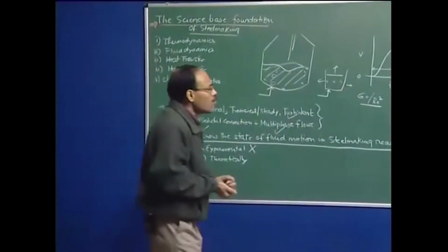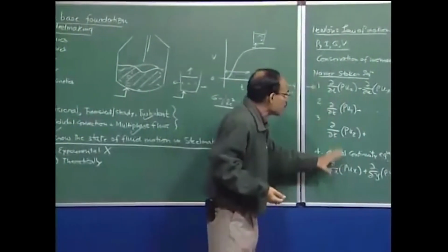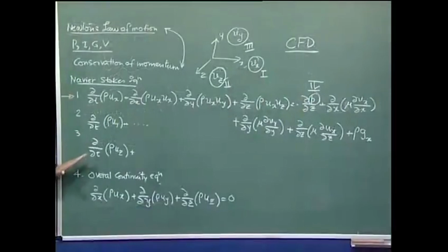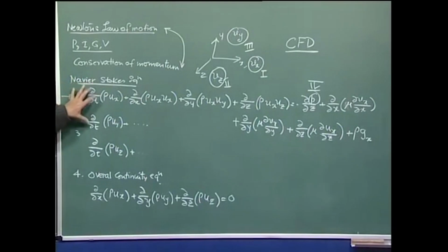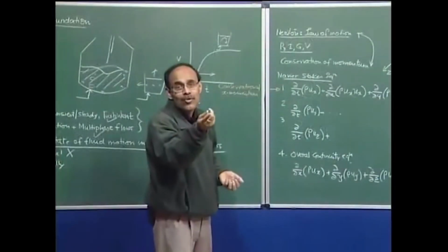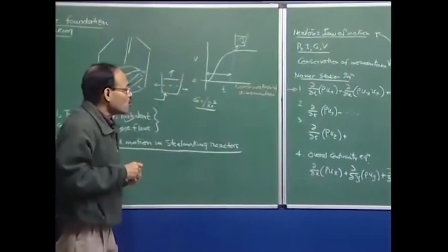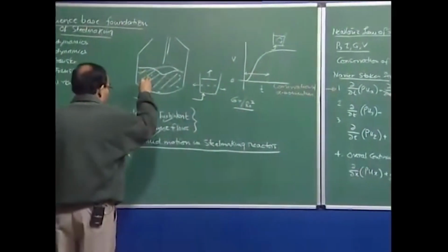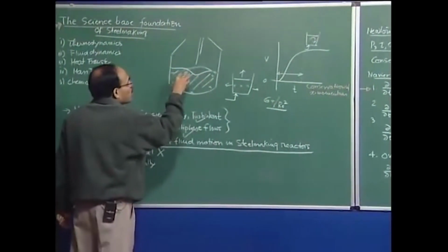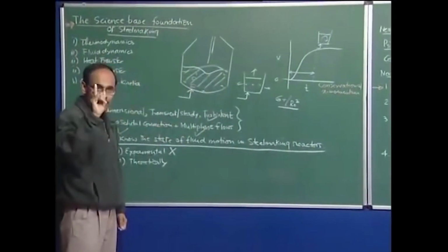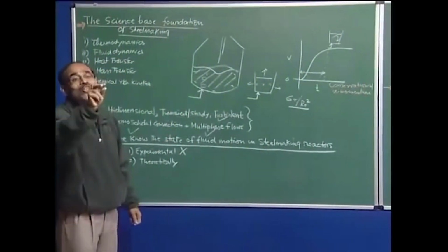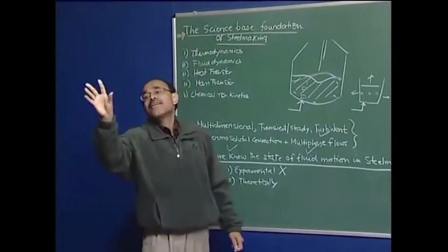Now, you can have just 4 equations, for example. On top of this, as I have mentioned, if you have thermal buoyancy, if you have solutal buoyancy, in that case the flow is going to be influenced by thermosolutal convection also. So, the flow is going to be related to heat transfer, and the flow of heat from one point to another is going to be related to fluid flow. So, if thermosolutal convections are important in this particular case, the flow will depend on the concentration gradient and on the temperature gradient.